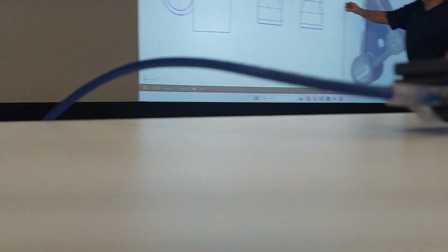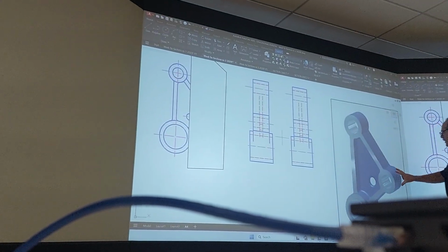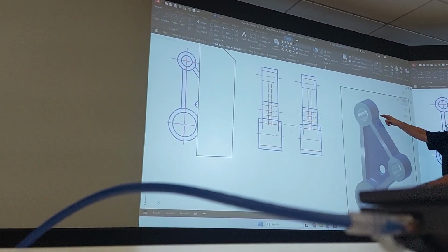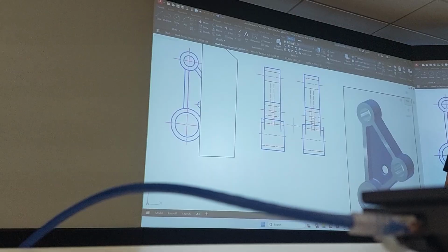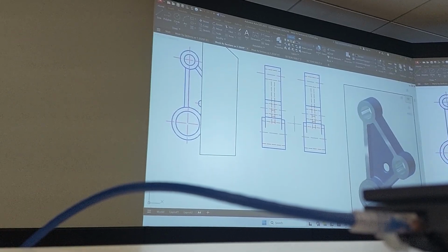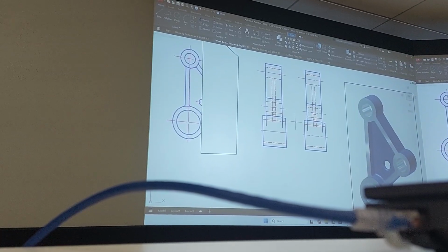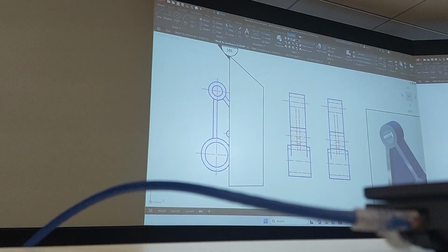We're looking in this direction, right? You can see this thing here, and then you see the top and bottom, the dashed lines indicate the holes. So now we've cut it, so now we want to draw a section through that cut area. If we're cutting it, we can just follow the section line down and see where the cuts are. So right here, that's a cut, right?